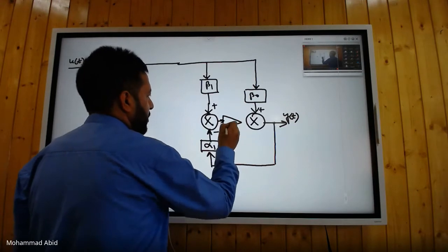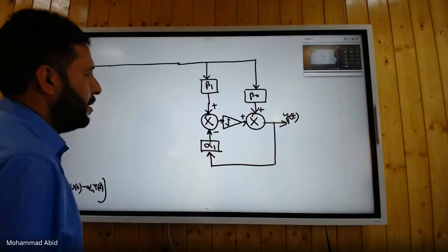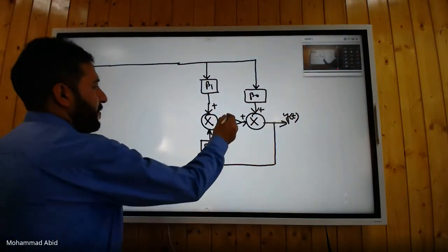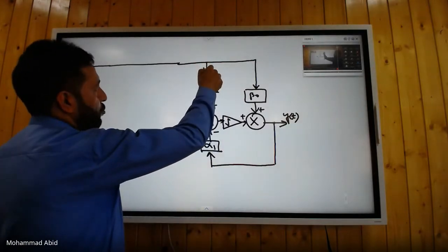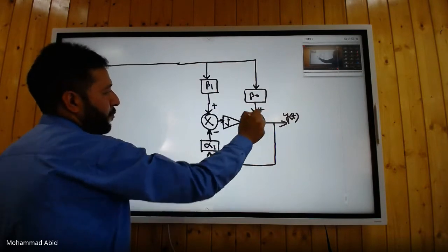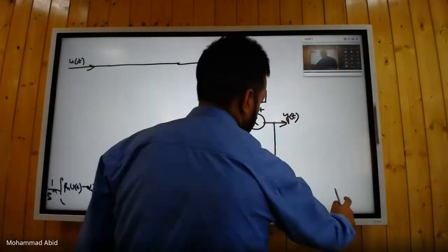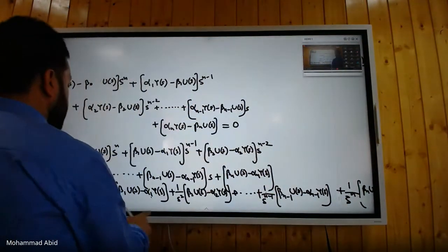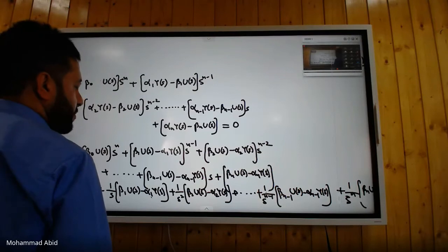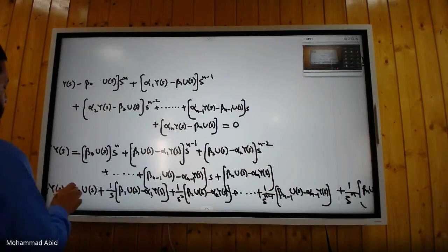We show an integrator like this. So it's like this. So this is plus here. This is the 1/s term in the Laplace domain. This is your beta 1 ut in the time domain. This is your alpha 1 yt, and I have replaced 1/s with the integrator. So I have represented this term in the simulation diagram. This second term here, this one. Could you understand this? Because my yt is not ut, this term is added to it. So I have just made this term on the simulation diagram and added it to this term.